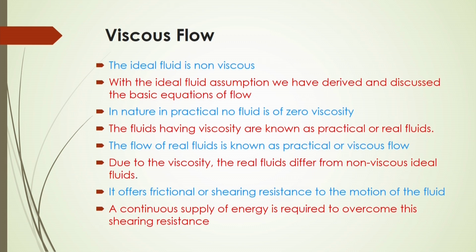We also derived the momentum equation and its applications in different processes, like how a jet pump works on the momentum equation, and what happens whenever fluid thrusts on a solid surface: how the momentum changes the fluid direction, and how the force is balanced by the solid surface in the opposite direction, as per Newton's third law.